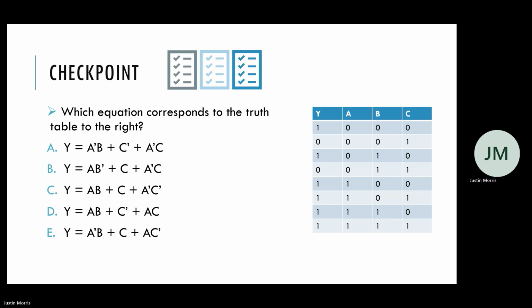So let's go over this together. I'll just show you how I like to do these kinds of questions. So this is sum of products. So we're working with min terms here, if you're talking about the language from the textbook. What I like to look for first is the simplest min term of these, and that is going to be just C or C not.